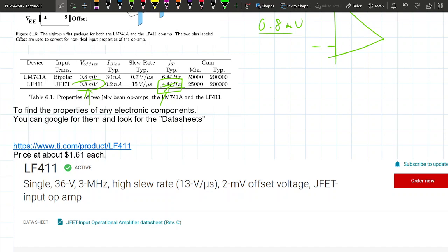This tells you basically what the input bias current is, 50 picoamps. I think previously a book says 200 picoamps, so this is actually better now. Input noise current, just some noise at the picoamp level. Supply current, it's just drawing some current from your power supply. And then you have the pin out. So you have the VCC here, the non-inverting input here, the inverting input here, and the output over here. And then you can even balance the input and output by putting a little bit of voltage there.